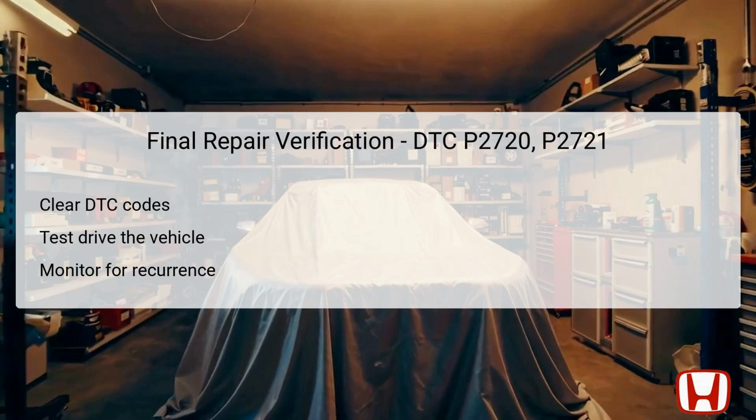To ensure that repairs related to DTC P2720 and P2721 have been successful, it is critical to perform a final verification process. Begin by clearing the DTCs from the TCM using the Honda Diagnostic System, which ensures that any stored error codes are removed. After clearing the codes, conduct a test drive under various driving conditions to ascertain that the transmission operates seamlessly, without any signs of erratic shifting or performance issues.